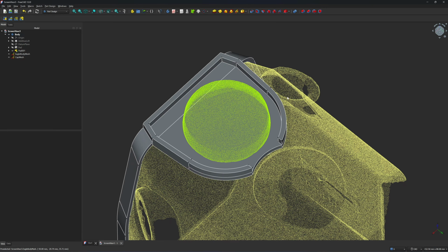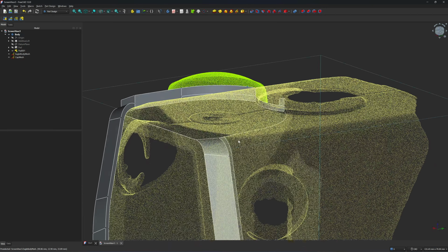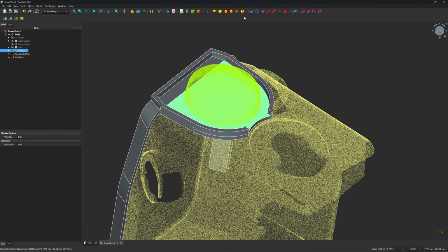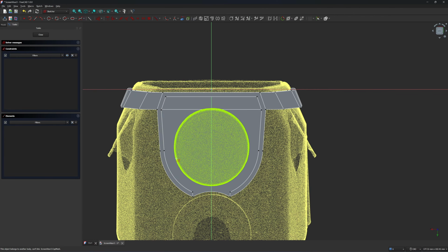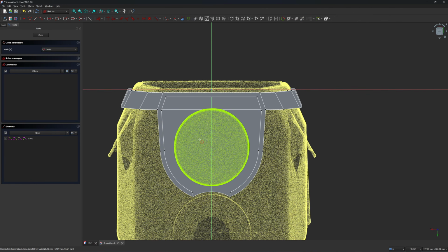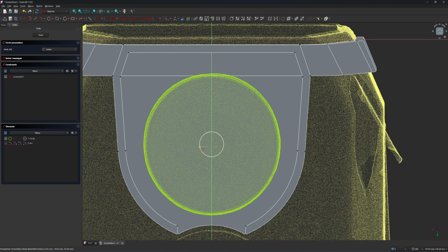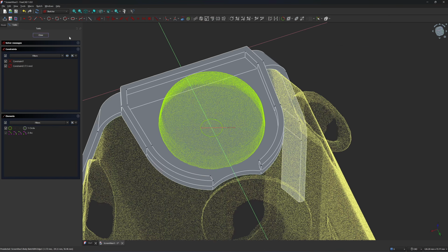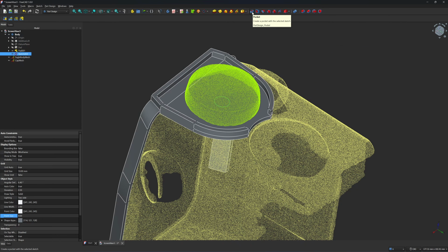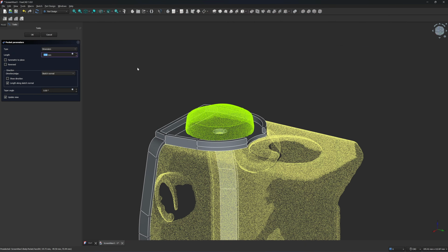Okay, next let's drill a hole for the antenna thread. Click on this plane, click on sketch, then I will reference this line, and then I should be able to find the center of the hole. Click on 7.5, close. I will cut the pocket to 5 millimeter.